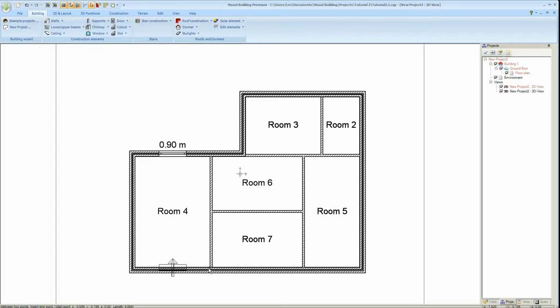You'll also see in the context menu keyboard abbreviations which you can use directly, meaning you don't actually have to open the context menu every time. For instance, instead of selecting center point, I can just press M on the keyboard. Control W also works with this, allowing you to select the snapping edge of the object that you're actually placing.